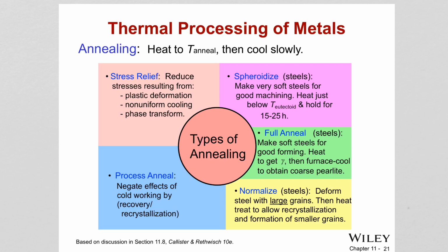What happens here, the alloy is heated to a temperature about 50 degrees above its austenite line, and then depending on, of course, what composition range you have, you might end up with an austenite or austenite and cementite phase, and then you cool it in the furnace by just turning it off to cool to room temperature, which will take a long time, right?